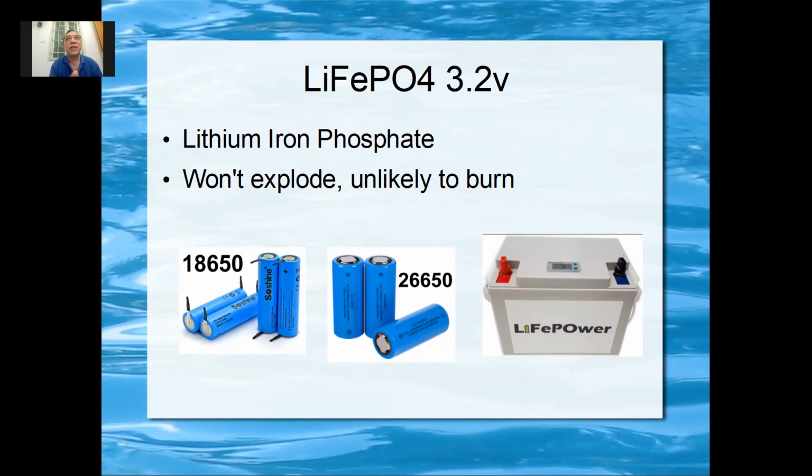So they put 15, so you got 1 battery short. And you want to charge this, you thought it's 16 battery, you put a different voltage, you charge, then you can damage it. So this one you have to be very careful. And for 48 volt, you also have to be careful, because if you touch the battery, you can get a shock. And it may not kill you, because 48 volt won't kill you, but you can get a shock. That's all. So just wake up. If you are sleepy, just touch it and then you wake up.